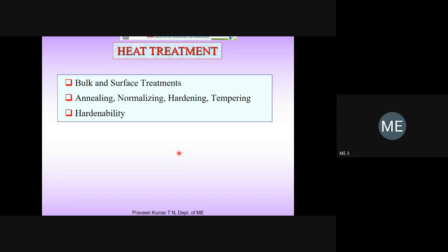Pearlite is an example of a non-equilibrium microstructure. Then you studied the bainitic microstructure yesterday. That also comes under non-equilibrium microstructure. Then there is one more, martensitic microstructure along with the austenite, another non-equilibrium microstructure. Anyhow, you have already discussed those. Everything comes under the bulk heat treatment process. In general, you have to remember the whole volume of the material is heat treated, not only the surface.